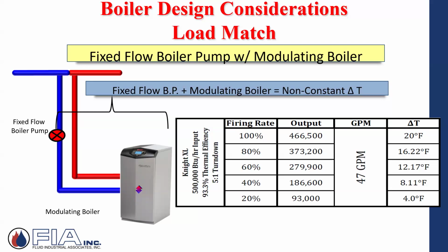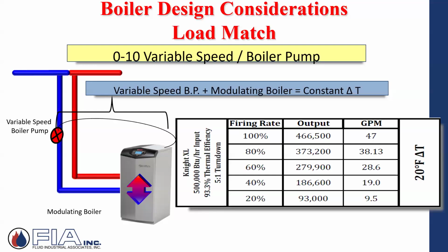And typically, when you have these high efficiency modulating condensing boilers, I want to bring them on and not shut them off, just modulate, simmer. So what they're saying here is the solution, or part of the solution, is to have the boiler pump be variable speed, controlled by the logic of the brains of the boiler.